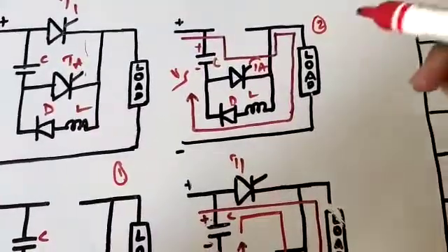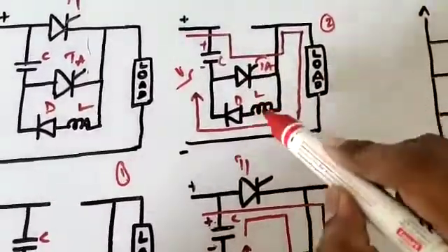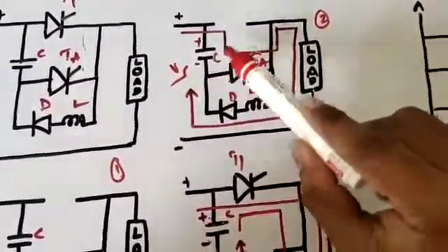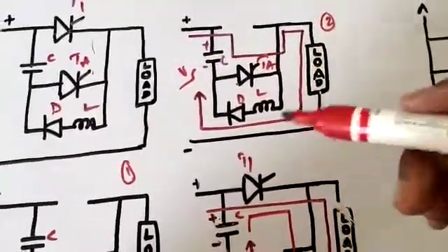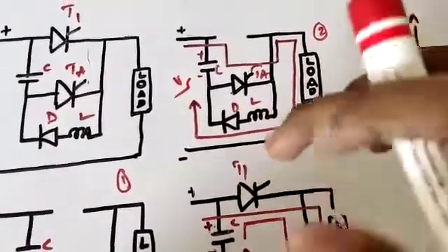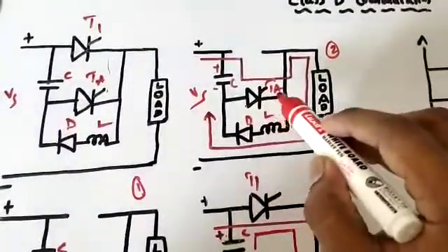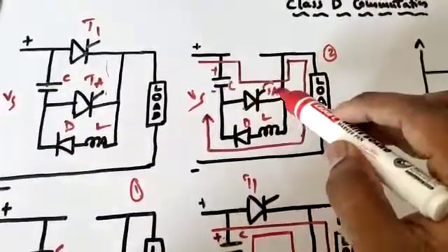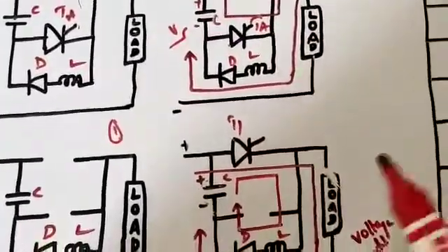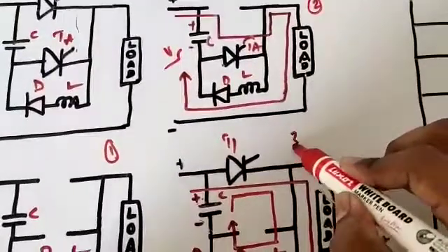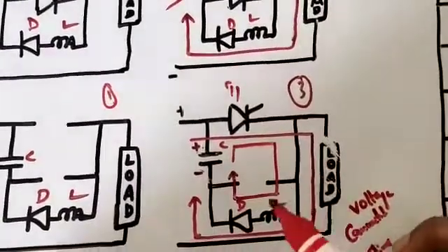As soon as the capacitor is fully charged, TA will turn off. The reason is that as the voltage across the capacitor increases, the current through TA, the auxiliary thyristor, decreases, since capacitor C and TA form a series circuit. That means the entire voltage is taken by the capacitor, so the current in the auxiliary thyristor decreases and it is turned off. This is the third one. As it is turned off, the corresponding figure will be as shown in the figure.